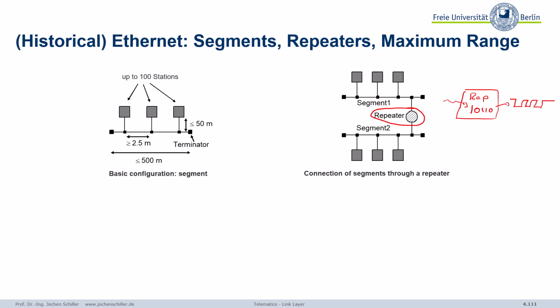So a repeater is not just an amplifier. An amplifier can amplify analog signals, so you have a weak signal, but it simply makes the signal strong. It amplifies also noise. With repeaters, I regenerate the original, hopefully the original data, and can then create a perfect new signal. And this is why, in theory, we can repeat digital signals for an infinite distance. So there's no reason why there should be a limit.